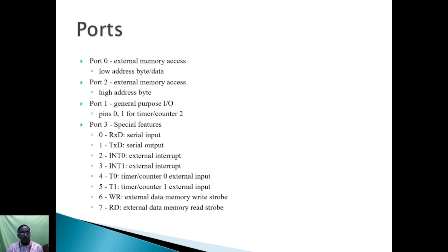So next one is ports. There are 4 ports: port 0, port 1, port 2, port 3. Port 0 is for external memory accessing the lower order byte. Next one is port 2, external memory accessing the higher address byte. Port 0 is also general purpose I/O.